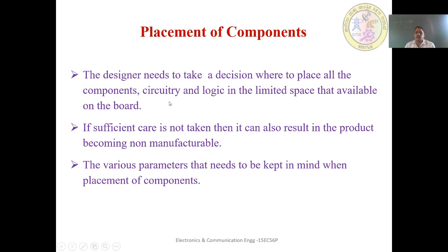The placing of the components and circuitry at a particular location on the PCB is a very tricky thing. That depends on how the PCB designer is placing the components. One more thing, the PCB designer has to keep in mind what the circuit operation is. If sufficient care is not taken, then it can also result in the product becoming non-manufacturable.